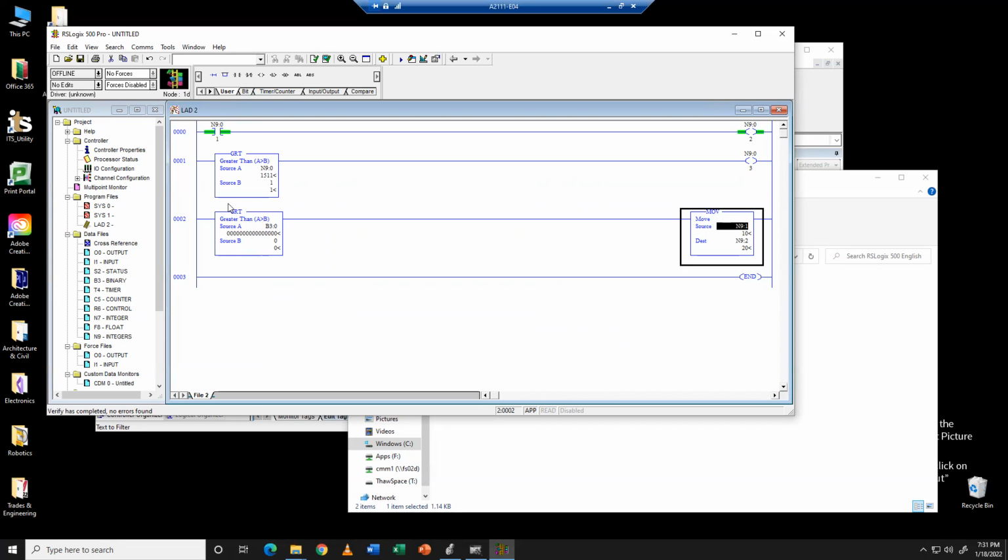for data collection would be if an event happens. So if you're trying to track your max and your mins, you could look here and go, if my current value is greater than my last max value, move my current value into my max value. So you can then move integer values around.